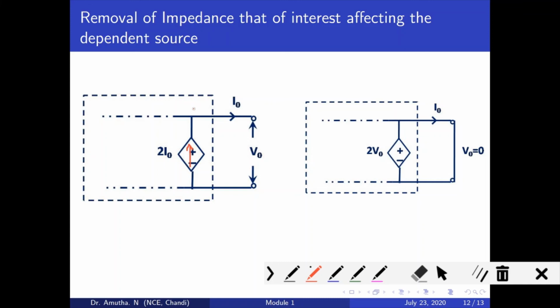But what we can do is, instead of taking this as the equivalent circuit, cut short here. Now you can find the equivalent circuit only up to this point. This point can be included in this equation, and then we can find the Z Thevenin, V Thevenin and IN.